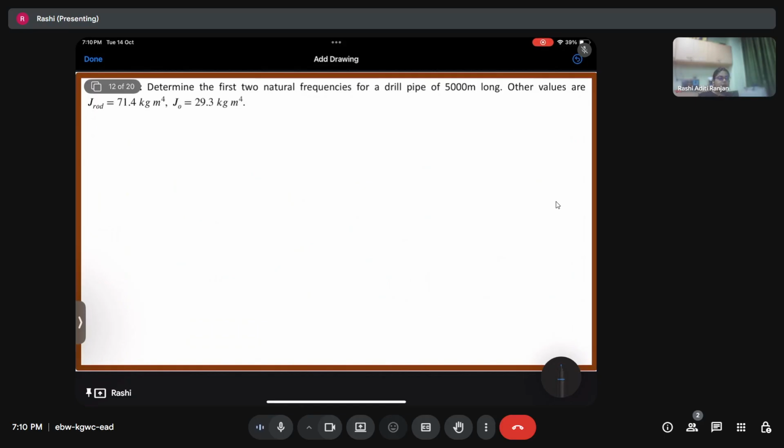Okay, so those patterns are going to show the mode shapes of the system. Basically, those patterns are because of the nodes that are present on the plate. If you put sand on it and then you start vibrating the plate, the nodes are going to be stationary with respect to time. So the sand is going to remain only on the nodes, and then you can see the shape of the nodes. It is a very interesting experiment.